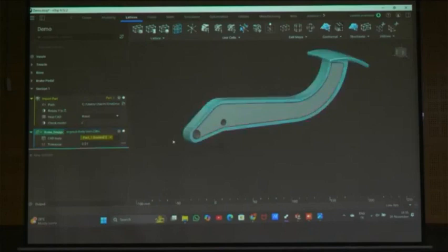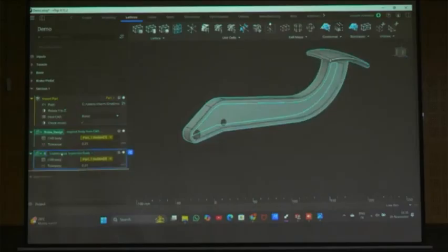And how to convert into an implicit body: press one time and you will get the face. Press again, double click on it, and you will select the entire body, okay? So one time I am selecting the face, I press two times, and I can select the entire body. Right click on it, convert, create body into implicit body. This is the brake non-design space, okay?